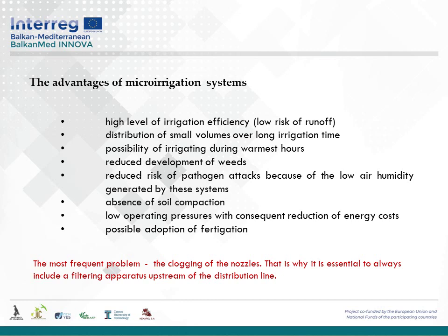The contribution of micro irrigation to increasing the air absolute humidity is minimal. This is because it is not the whole surface of the greenhouse that is irrigated. There are only spots of wet soil, and therefore the evaporation rate will be significantly less compared to furrow irrigation, for example, or even common sprinkler irrigation.